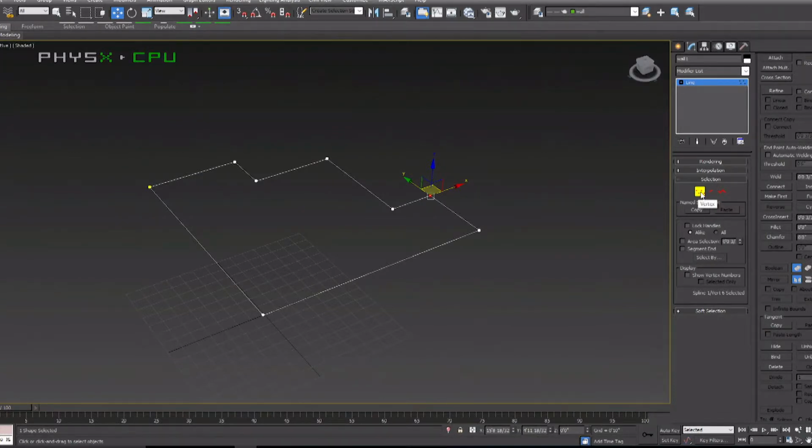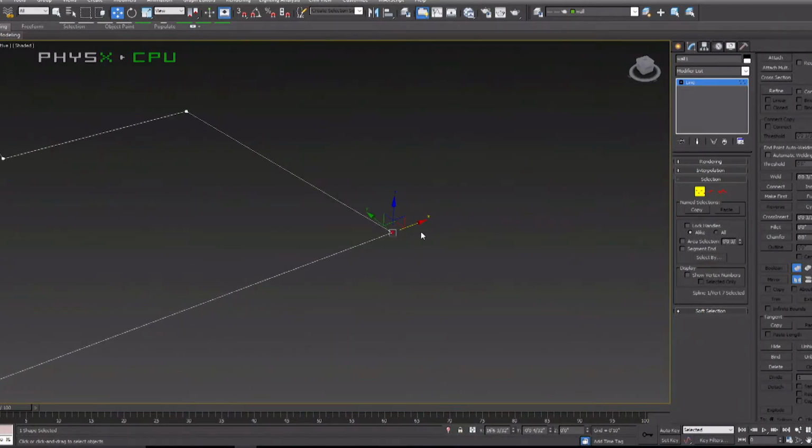And then, for example, if you want to play with the vertex here, you click on the vertex and you start moving them. So you click on that and move it based on the axis you want to move. For example, if I want to move it over the x-axis, I have to hover the mouse over the x-axis, and I drag and drop the vertices. That will allow me to go only on the x-axis, not any other axis, and that will limit the mistakes.